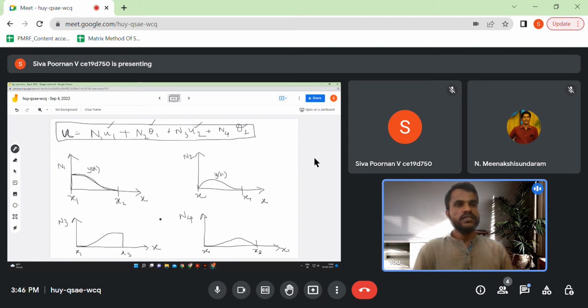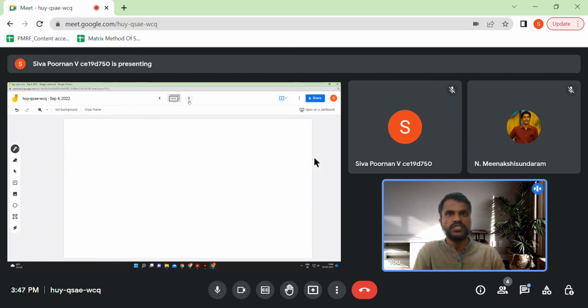Fine. Moving on, this completes the whole discussion of analyzing beams using stiffness methods. Frames are not going to be significantly different from what we discussed in beams. It's just an addition of the problems of trusses and beams. In trusses we had only axial forces. In beams we have shear forces and bending moments. So in a frame problem, we will have axial forces as well as shear forces and bending moments, right? A mixture of these two put together is a frame structure.